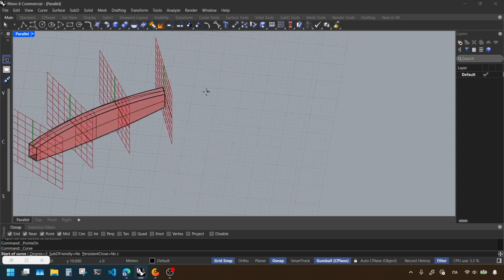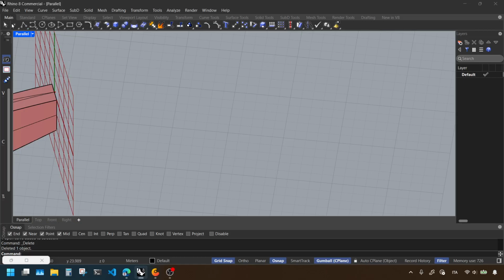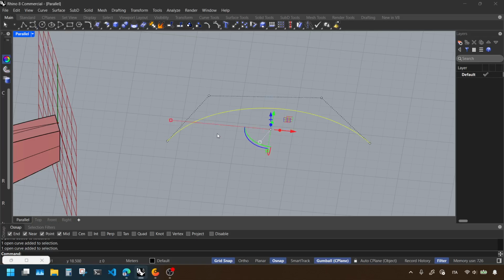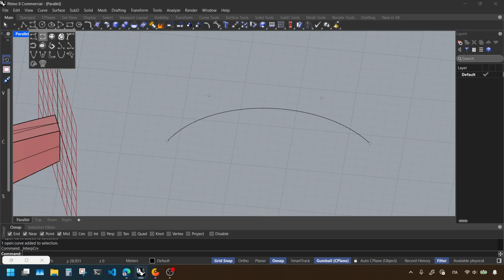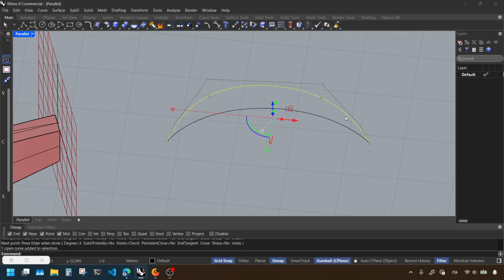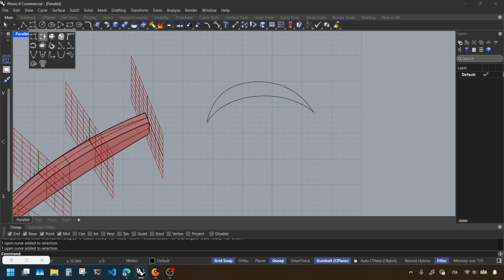It is exactly the same as when you do a NURBS like this. So you define the control points, okay? Or let's actually draw the points first. So we draw the points first. You can create NURBS by using these as control points, and you'll see that most of the control points will not be part of the curve. Or you can use, and this is the same as doing loose when you do the loft, or you can do this one, which is passing through the points. So it will generate new control points so that the curve passes through those points. And this is the same as using, it tells you when you draw it.